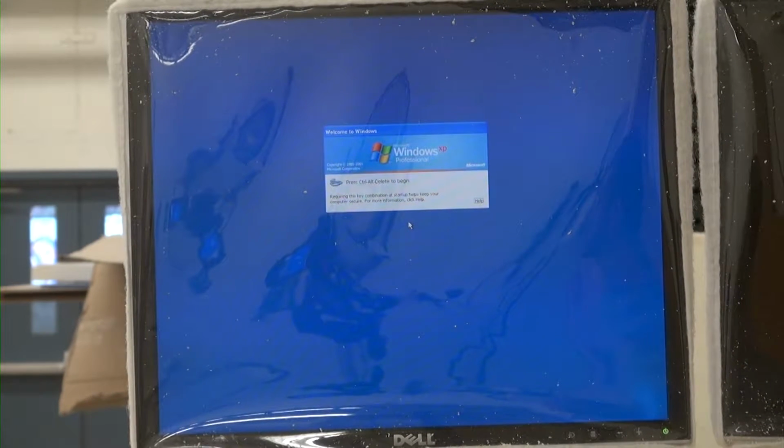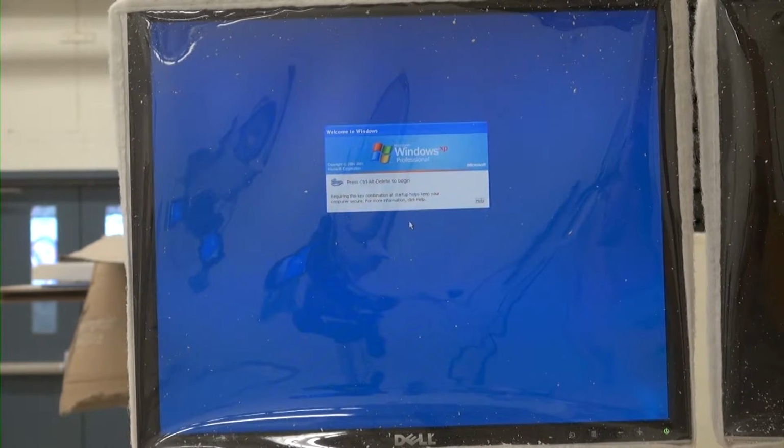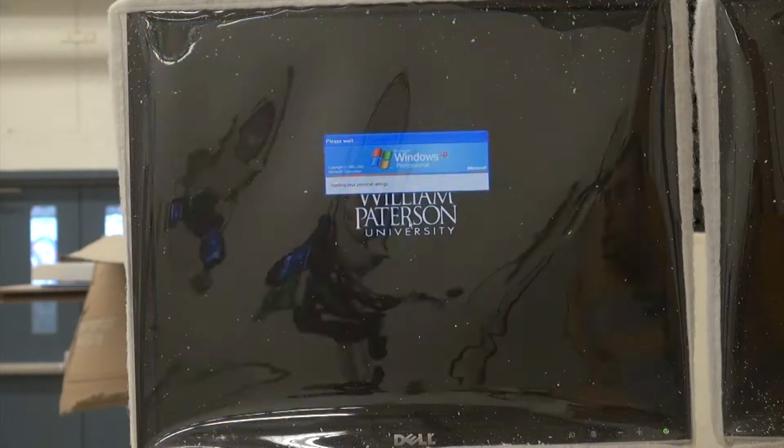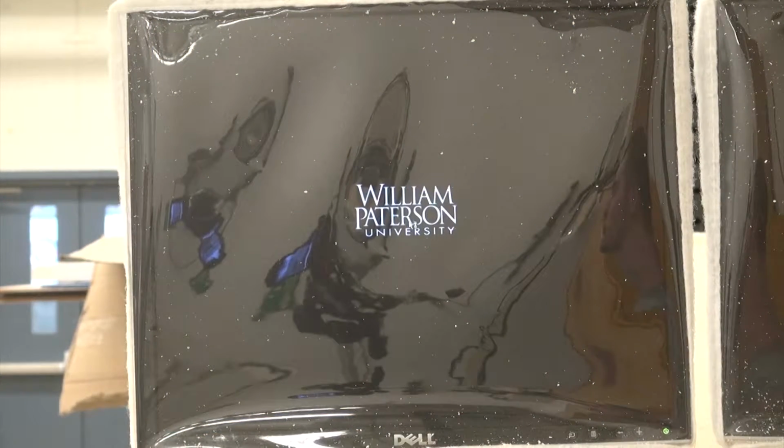Okay, here we are going to actually run our file on the mill. I've been told that this computer down by the CNC might actually get updated or replaced in the near future, so if this video is outdated, I apologize. First of all, the password is the same as the login, which is milladmin, all lowercase. This computer has to use Windows XP to run EasyRouter, which is the software for the CNC machine.